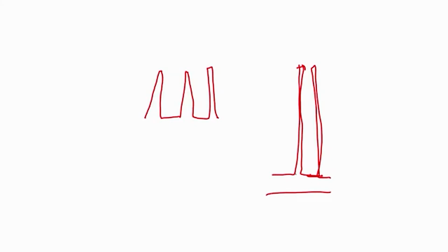This type of fin, where you have a long deep fin and an adjacent very small gap, is useful in the case of natural flow or where the velocities are small, because there is enough flux available and enough time for the fin to reach the same temperature throughout.